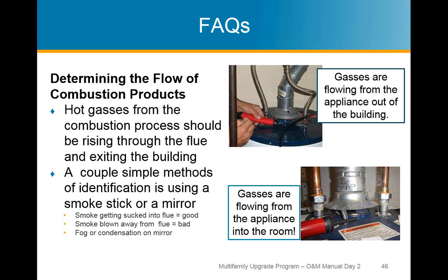If the smoke is getting gently sucked into the flue, everything is working properly, more than likely. If the smoke is just sitting there or getting pushed out into the room, then that's bad. It's a cause for concern. That would be when you call in a professional, or call the manufacturer, or activate one of those warranty concerns and get someone out to look at that equipment and make any corrections as needed.